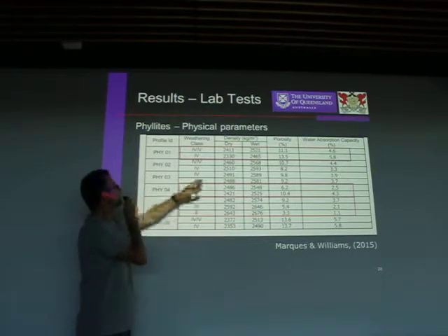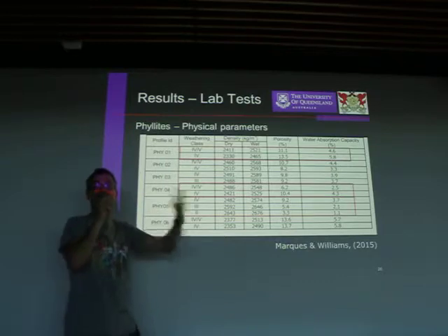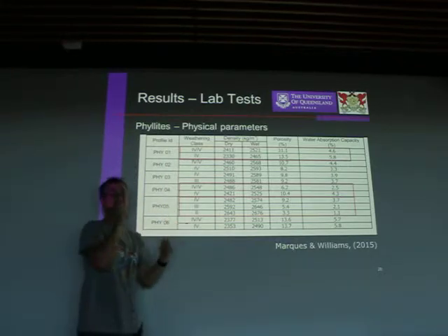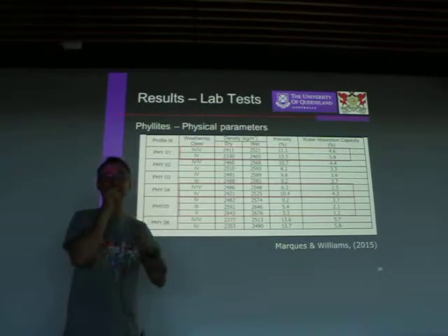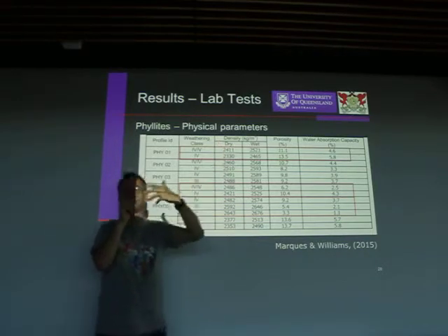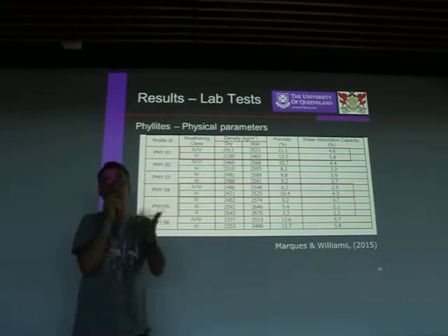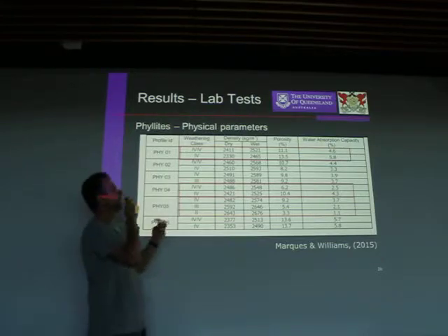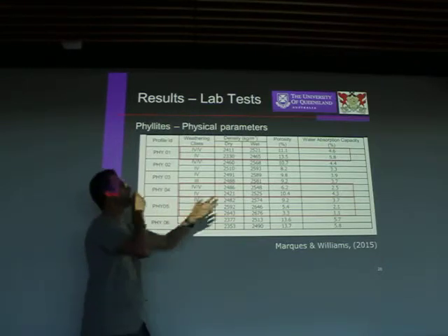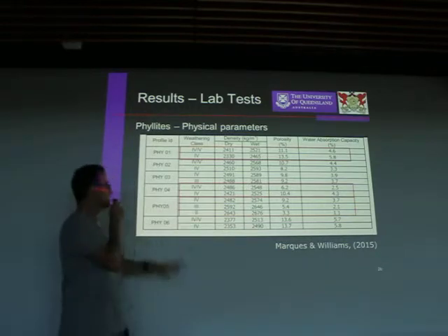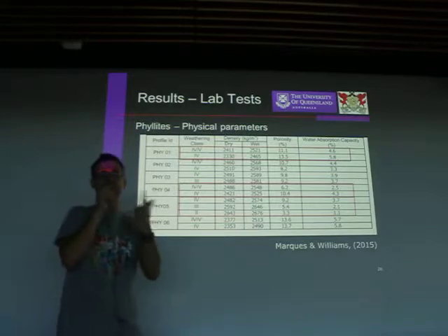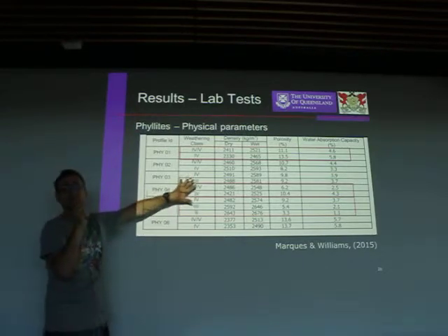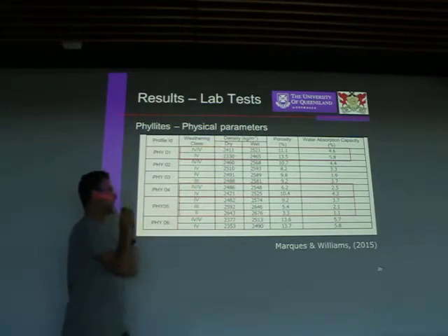What happens is that for the more weathered layers, in this case of phyllites, there is a lot of biotite in these phyllites that I will show you later. And these biotites free lots of iron oxide. This iron oxide gets into the openings and the voids of the weathered rock and increases the density and reduces the porosity. So it's a specific behavior of phyllites that I have found one paper in the literature that achieved the same results.